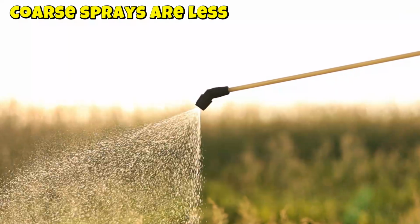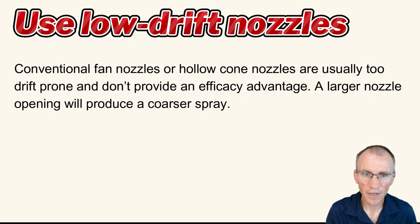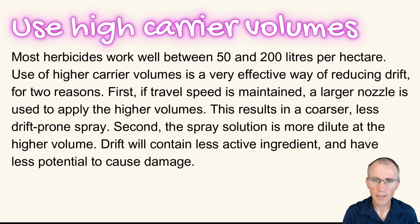Remember, coarse sprays are less prone to drift than fine sprays. Use low drift nozzles. Conventional fan nozzles or hollow cone nozzles are usually too drift prone and don't provide an efficacy advantage. A larger nozzle opening will produce a coarser spray. We can also use high carrier volumes to reduce drift.